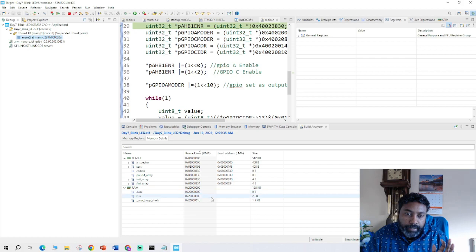If it is in RAM, it will be a virtual memory address, and if it is in flash, sometimes it can be both, but as you can see, both the addresses inside the flash will be the same address. So that's why it's called load memory address, and this is a virtual memory address. So this is the difference between LMA and VMA. LMA is the load memory address that's situated in flash, and VMA is the virtual memory address that lives in RAM.